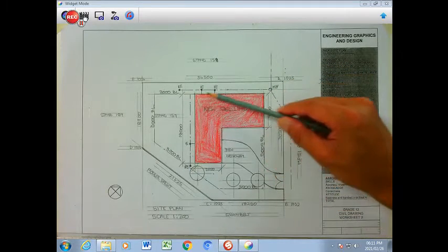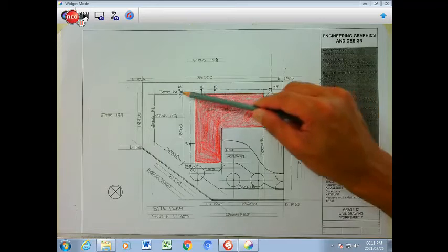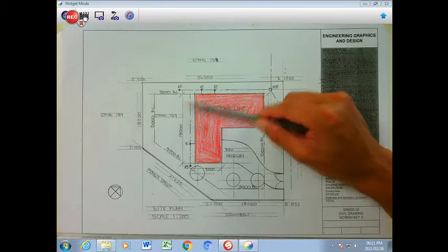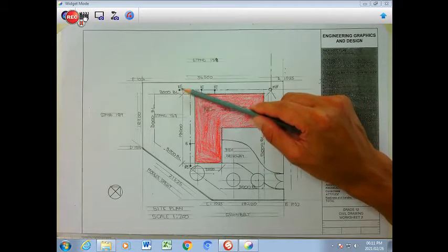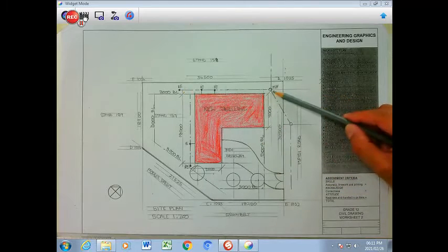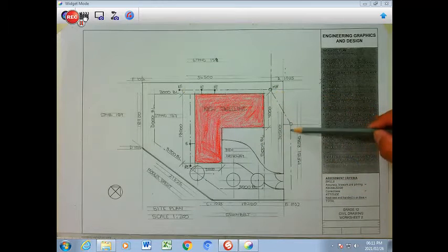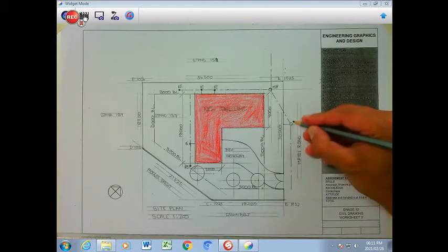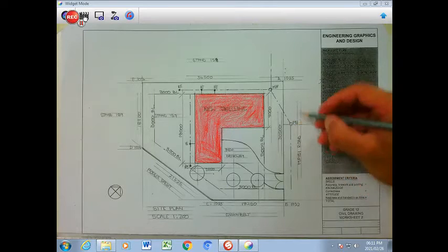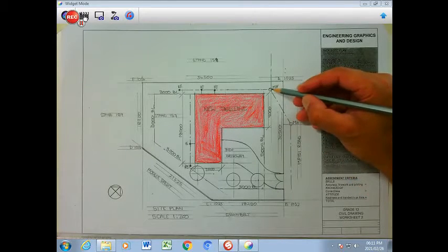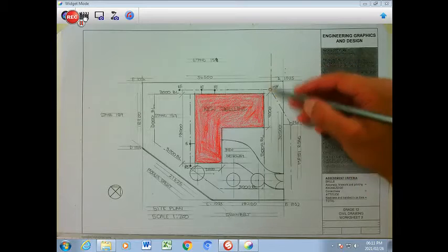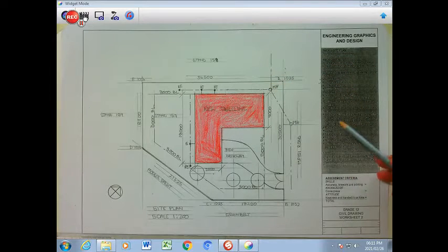We have 3 IEs, which you can place anywhere, and we have 2 rodding eyes, which would be the start of our sewer line, and it runs to a municipal manhole outside in the road here, MH, the manhole, and this is the manhole inside your property. Okay, that has been drawn as well.